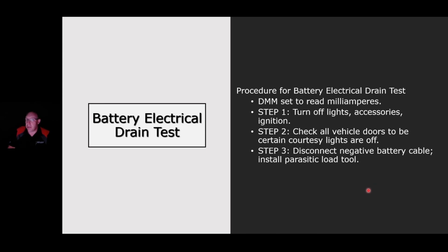So the video on the Power Probe hook, you'll use the hook to do a parasitic drain. You'll also use your digital multimeter, and the amp meter in your digital multimeter, to do a parasitic drain test, okay? So you're going to have a lab sheet on that. You're going to have to do that. I expect to see you do it right.